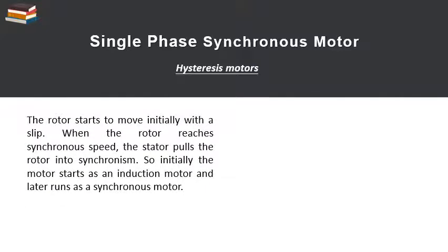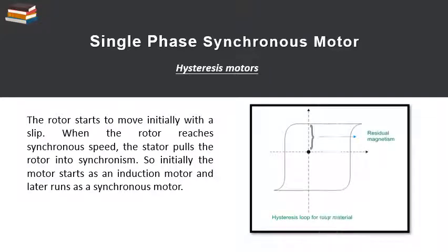The rotor starts to move initially with a slip. When the rotor reaches synchronous speed, the stator pulls the rotor into synchronism. So initially the motor starts as an induction motor and later runs as a synchronous motor.